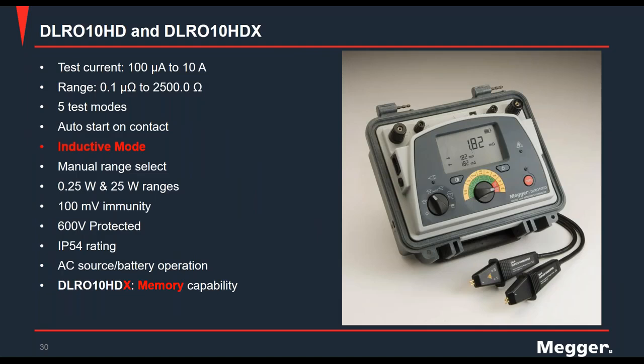So let's look at the DLRO 10 HD and the 10 HDX. These devices support a test current of from 100 microamps to 10 amps. And the resistance range that they can detect goes from as low as 0.1 microohms to about 2,500 ohms. These test equipment have generally 5 test modes that we talked about, where you have the normal, the automatic unidirectional, the continuous, and the inductive.